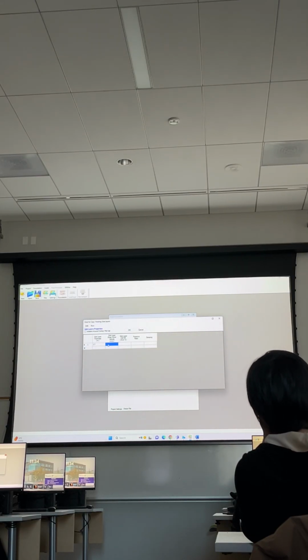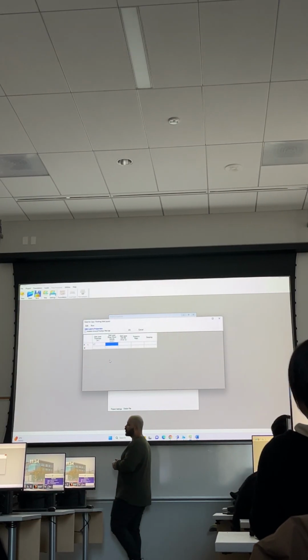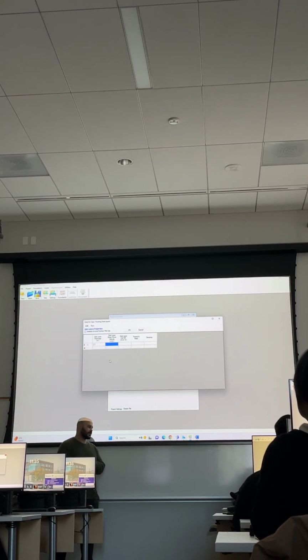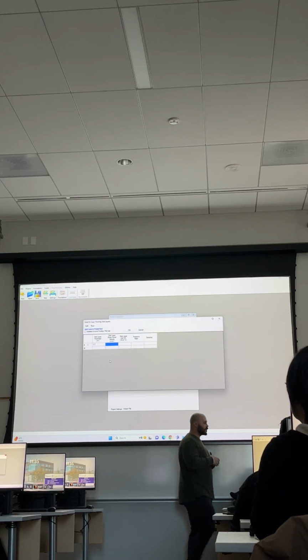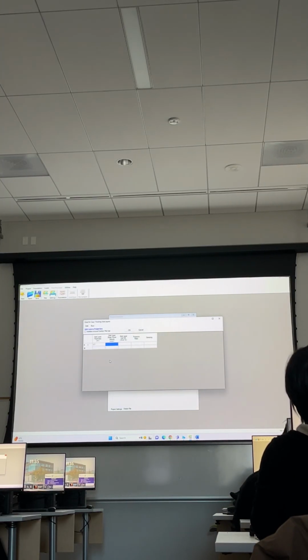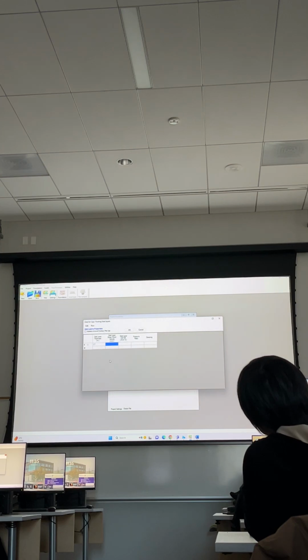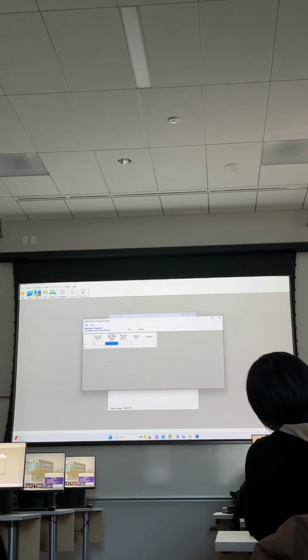Okay? For the side layer shear wave velocity, usually we choose the side layer because it's not the original soil. We're going to use soil of our choice. You may use granular soil, structural fill, or CLSM. There are multiple choices you can choose from. For this example, I'm going to assume it will be granular soil.